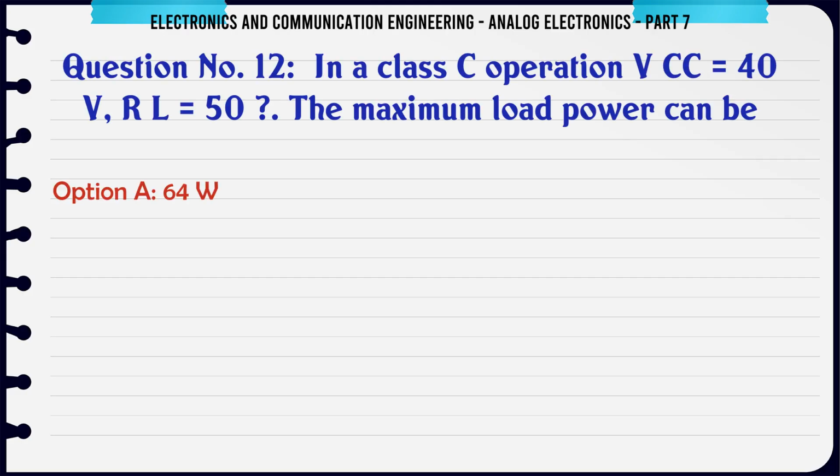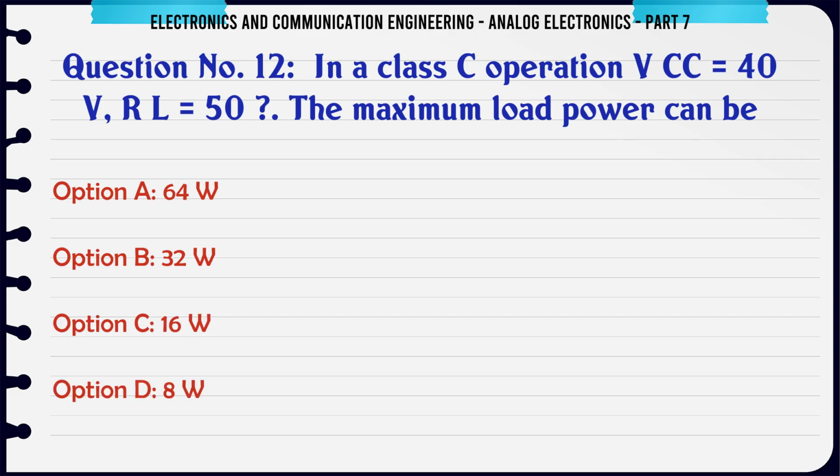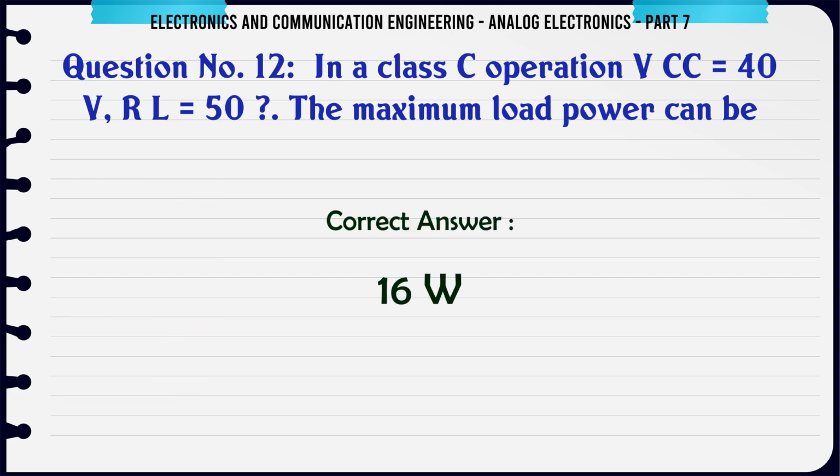In a class C operation VCC 40 V, RL 50 Ω, the maximum load power can be A. 64 watts, B. 32 watts, C. 16 watts, D. 8 watts. The correct answer is 16 watts.